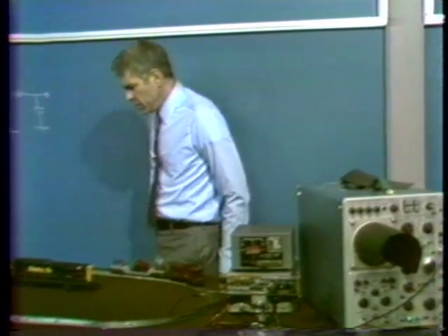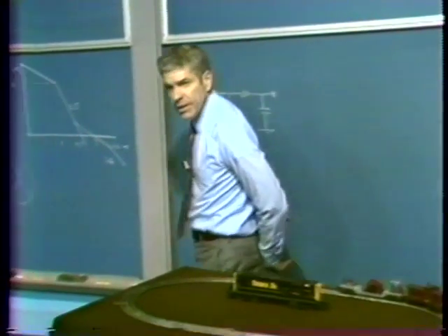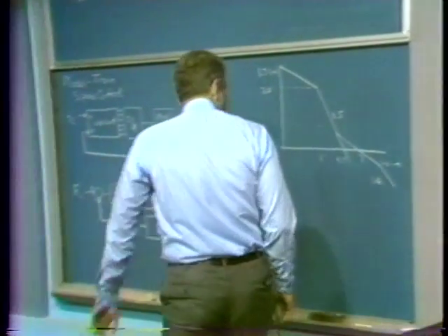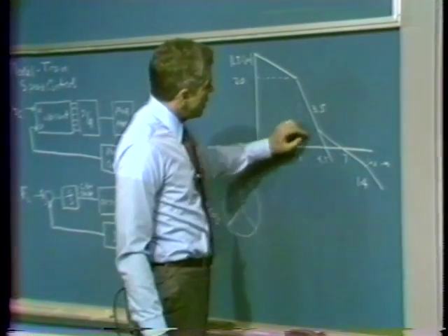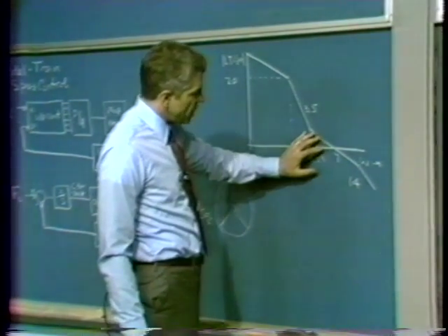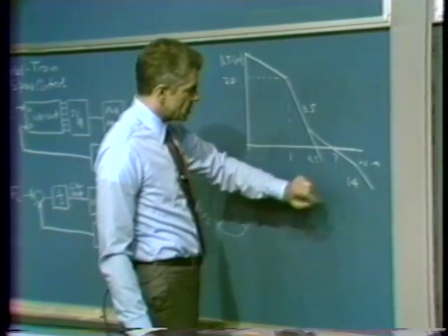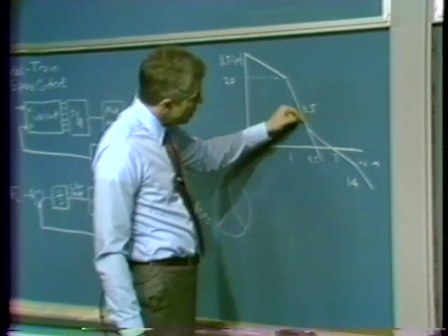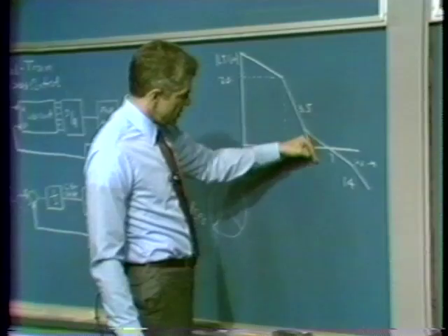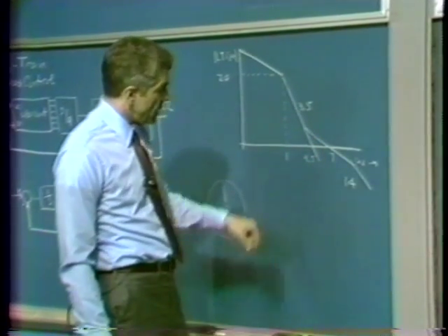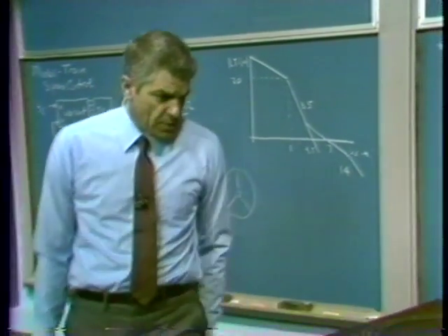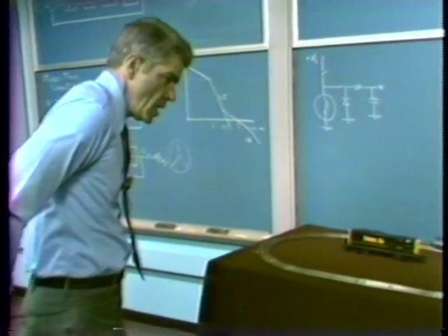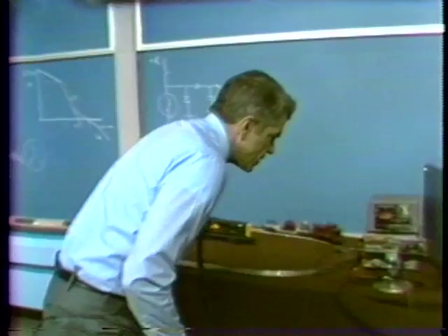What I will do is get rid of the lead network that gives me this characteristic by simply removing a capacitor, which is responsible for giving me this lead type transfer function, so I can end up with this sort of loop transmission magnitude, a system that has only 12 or 15 degrees of phase margin. I do that by removing a capacitor.